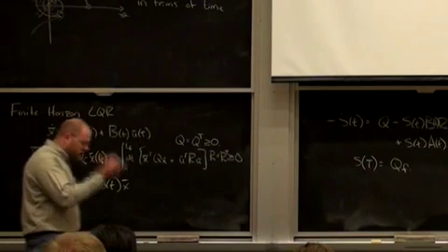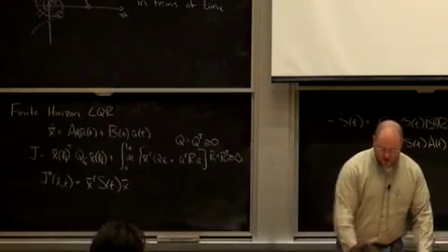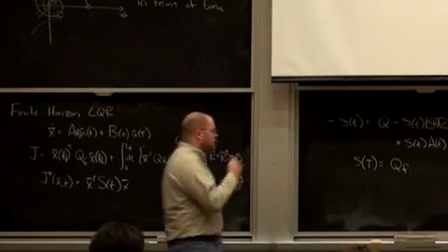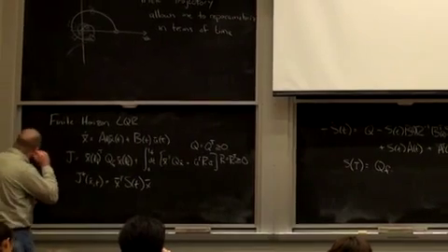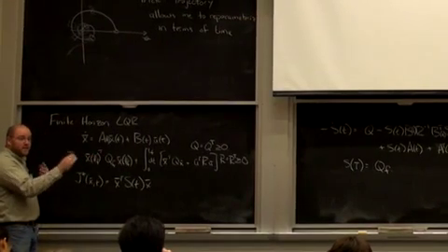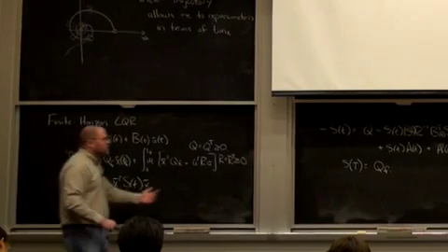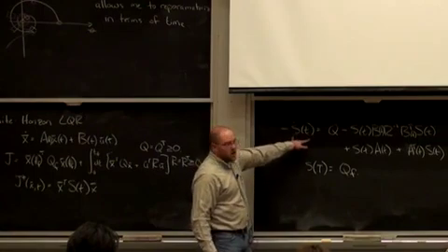Okay, so the LQR you know and love that you've used in MATLAB is the time invariant infinite horizon LQR, right? I told you that if you cared about a finite horizon and you had a time invariant linear system, then suddenly you couldn't just find the stationary points in this. Remember, MATLAB's solution just tells you the long-term behavior of S.